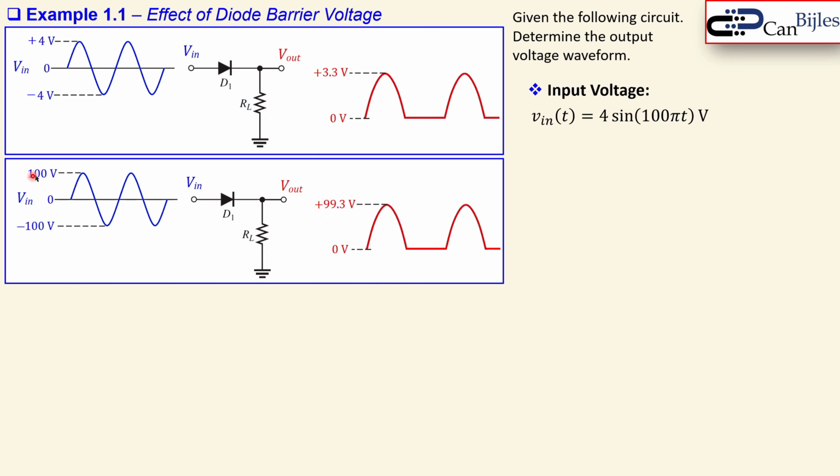That's also the case if you have very high voltage applications. That 0.7 or maybe 0.9 or 0.8 volts loss is not really a problem. So in this case, the input voltage is 100, same frequency. Now you can see this as a percentage is not a really big problem here, the 0.7. But if this is, for example, 2 volts, then it is a huge problem, of course.